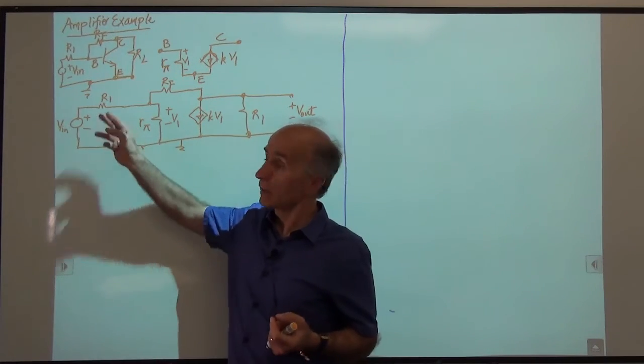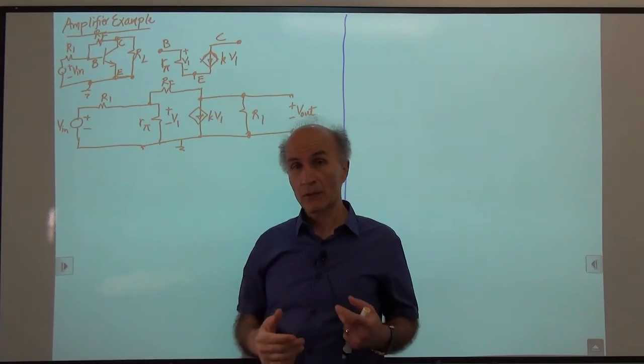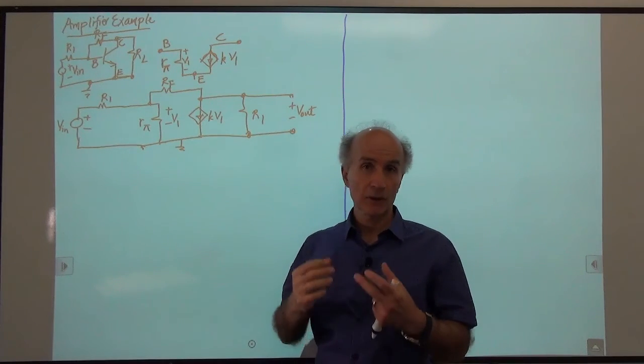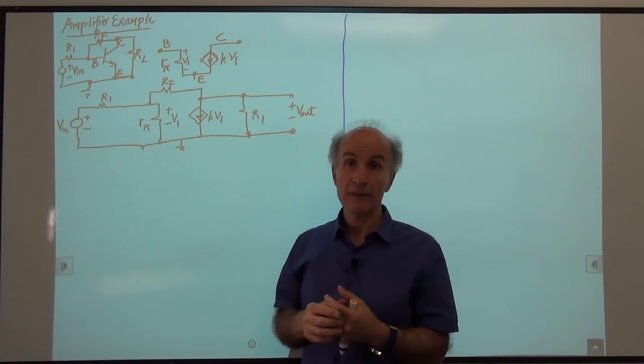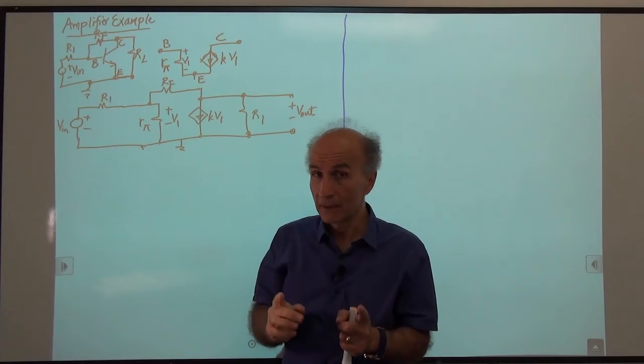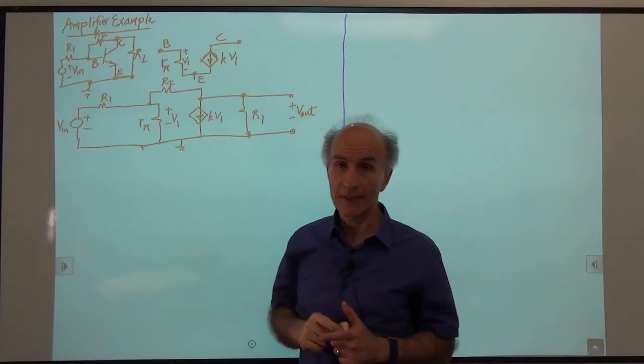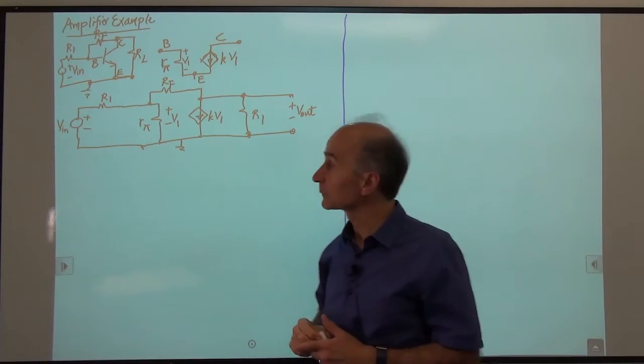This is what you might call the Thevenin resistance or output resistance or internal resistance, but that's the Thevenin model of the microphone. The microphone is not an ideal voltage source, right? It's not just that. It also has some resistance, equivalently.